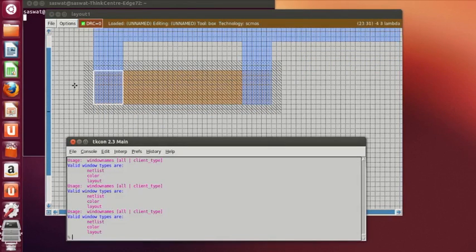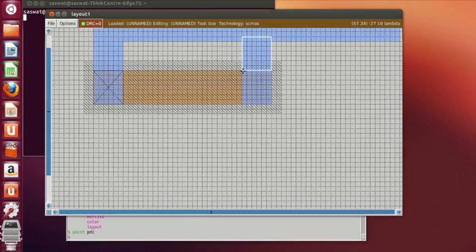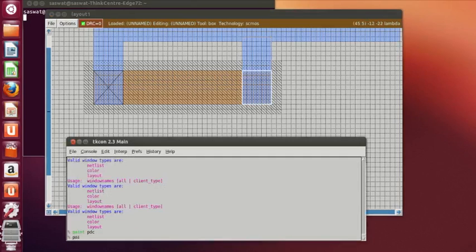Since we have the diffusion layer and metal layer, so type paint. Since this is P diffusion, then P diffusion contact. So we will type paint PDC in order to place a P diffusion contact. Similarly, over here also select the area and type paint PDC.